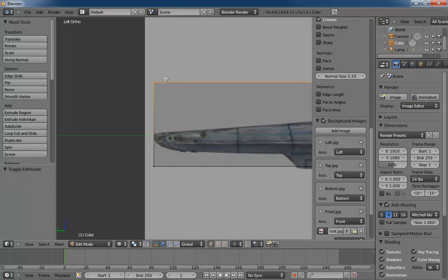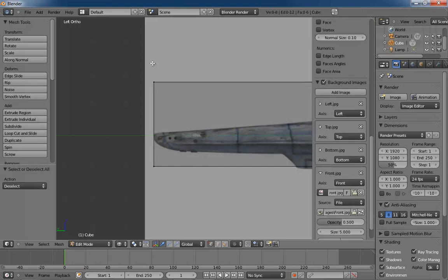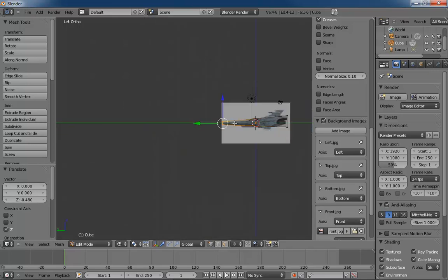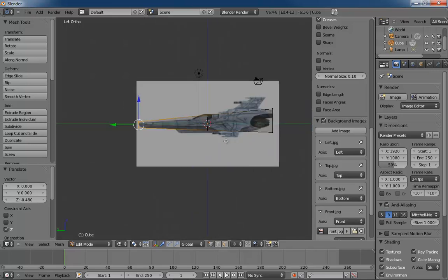So what I'm going to do is grab our box. Let's hit Tab to go into edit mode. Let's grab these front vertices. So I'm going to hit V and drag out a marquee selection box right here at the front, and then I'm going to hit S and scale these down. Then I'm just going to slide them down a little bit. So we're tapering the entire box for just a moment, turning it into kind of this wedge shape. Now here's why I'm doing that.